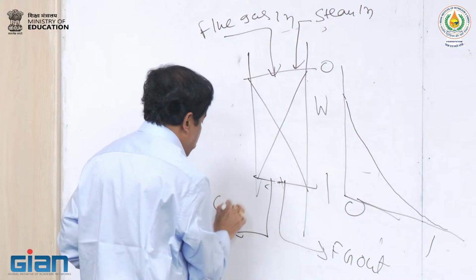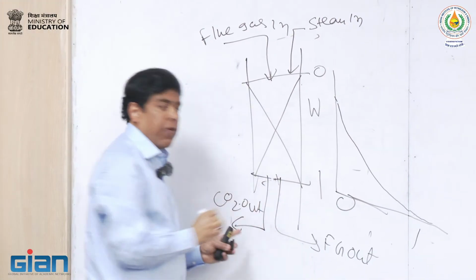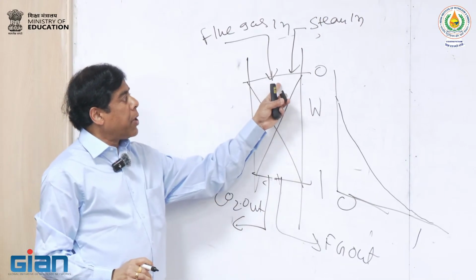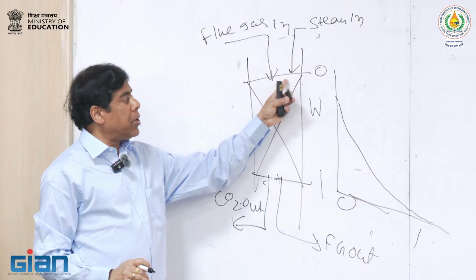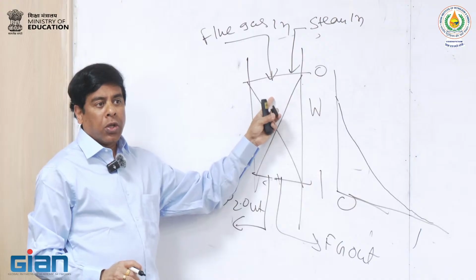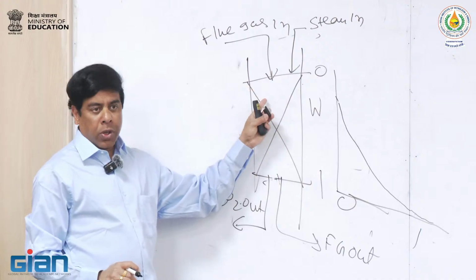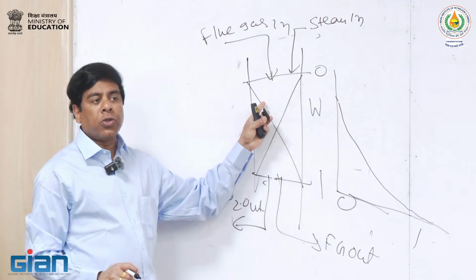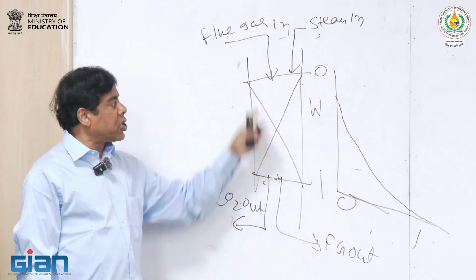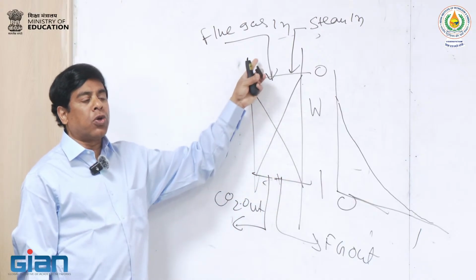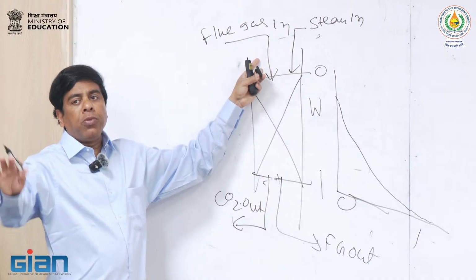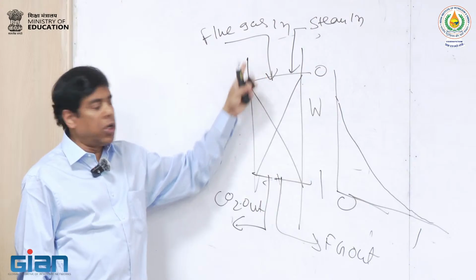Now, when you start desorbing, say I'm trying to desorb in this direction, so I say steam in, and then CO2 out. With a configuration like that, steam desorbs the CO2, because this portion has very high CO2 loading. The moment the CO2 is desorbed, it has a very high partial pressure of CO2, and that CO2 can adsorb here.